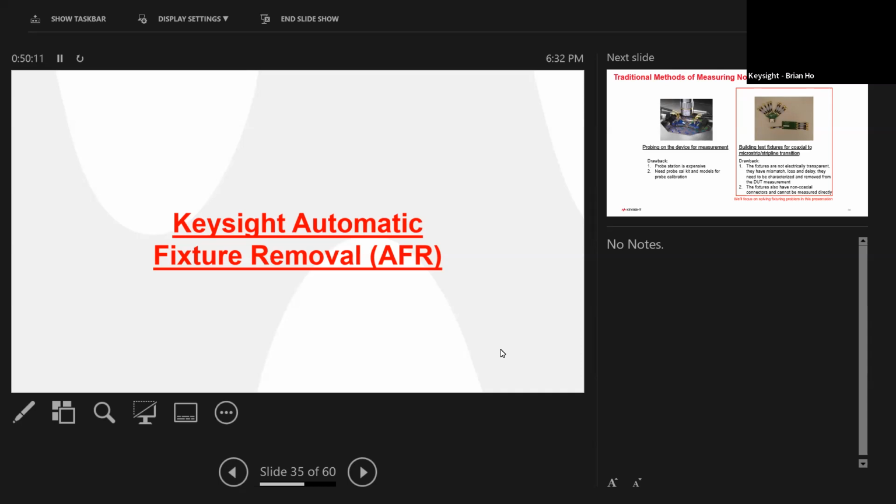I'm just trying to think. So essentially what they're saying is they have a test cable and then they have a semi-rigid cable connected to the test cable. They want to make sure the test cable plane is moved to that one point, and that the cable is heated, they said, right? Or the measurement. It says rigid cables have dielectrics that expand when heated. This changes the Z0 of the cable. How would you suggest moving the calibration plane to the end of the cut semi-rigid cable pigtail?